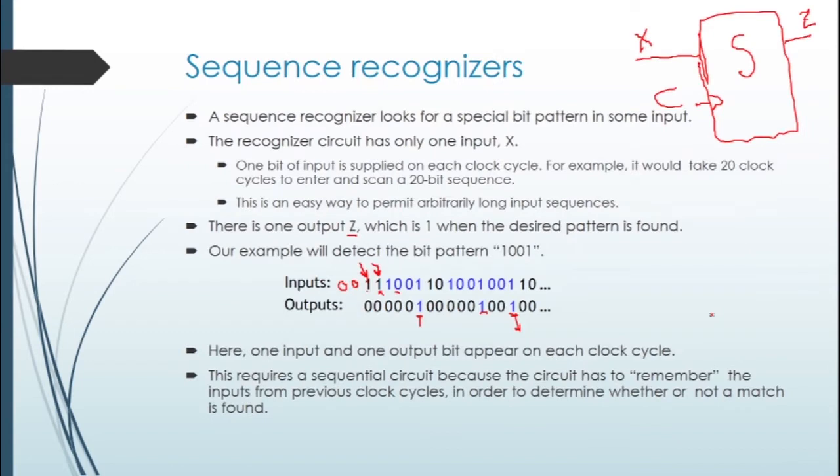If we have got a pattern like this, 1 0, this is state B, state C, then state D, and after state D there is another 0, this means the pattern is broken. We don't have the pattern here, so it will go back to state A where the sequence has not yet started. If there is a 1 here, that means our pattern is completed.